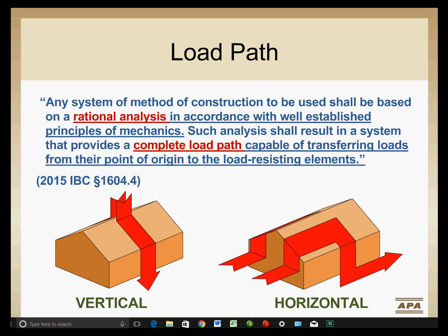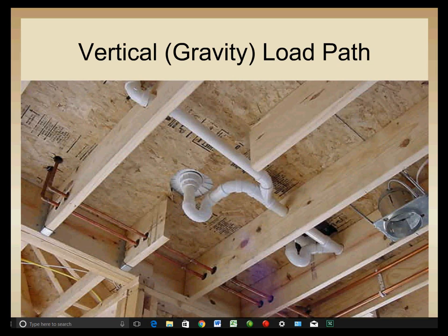What's important to note from this quote is that establishing and analyzing a load path is based on rational analysis, and a complete load path should transfer the loads to the load-resisting elements and eventually to the foundation. So vertical or gravity load paths are fairly intuitive, and it can be easy to see when a vertical load path is incomplete, as evidenced by this picture. So the focus of today's presentation is going to be on the lateral load path.